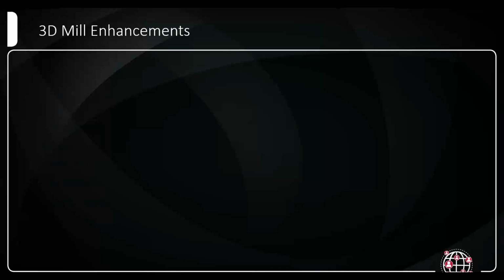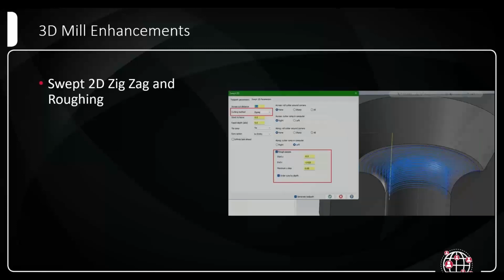Now we're going to get into the Mill 3D enhancements. First, this one caught me way off guard. I was not expecting to get some enhancements to Swept 2D. Don't get me wrong, I love Swept 2D, but definitely a happy surprise to see that it gets some more enhancements. So Swept 2D can now do zigzag passes as well as one way. And on top of that, it can actually do some roughing. So for those of you who don't necessarily have a 3D license, for simplistic features like this fillet I've drawn here, you could get away with doing some roughing with Swept 2D now in 2024.